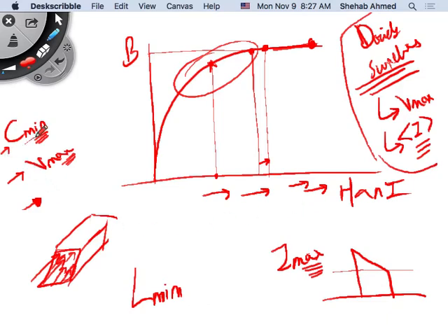Capacitors, we have to first choose the minimum value of capacitance, which considers ESR. Okay, it considers ESR. And then we have to do what? Of course, the other main parameter is Vmax, because it's going to dictate the breakdown voltage of the dielectric material. Right? And then what's the other main parameter? Something that causes heat, temperature.